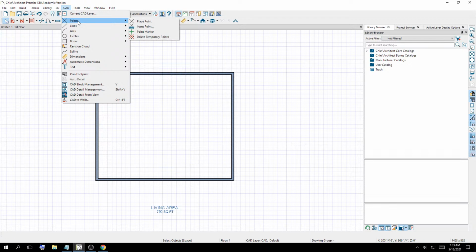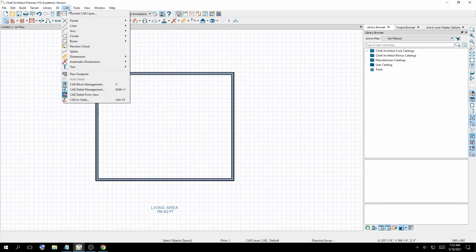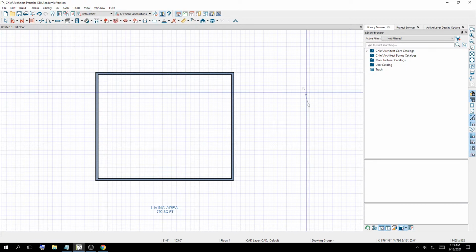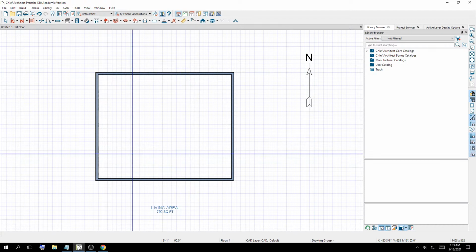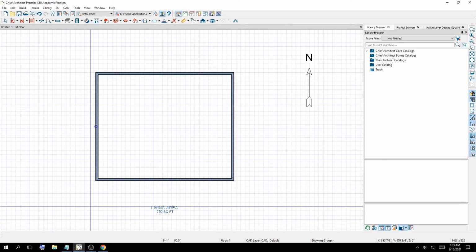If we go to points, bear with me for 1 second. There should be a north pointer, and we could actually indicate what direction, and then when I say north, east, south, and west, you'll know exactly what I mean. But it is in this area. We could place a point, lines, here we go. So under lines, if you scroll down to north pointer, I'm just going to click and drag and say that that's north. Okay, that way I could say that this is the north facing side, this is the south facing side, east and west facing. So now if you're in the northern hemisphere, you know what side the sun is going to rise and set. You know what side is going to be colder and warmer, right?